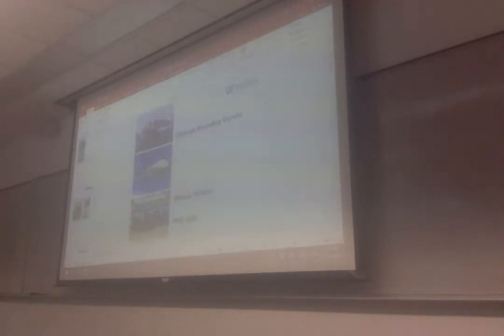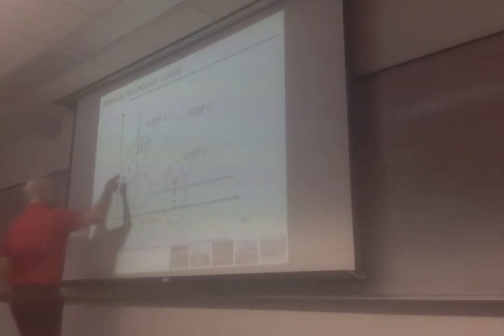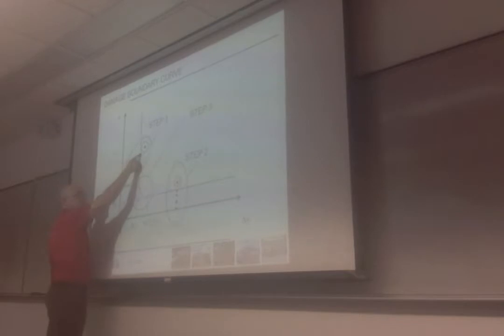Sorry, I'm going to go back to that last slide here. By increasing the drop height from test to test, you increase the velocity change, because with a higher drop height the impact velocity is going to increase, and you increase the acceleration as well because you have a larger velocity change over a constant time. So you go this way, and you don't have damage. Here you have damage. So the conservative approach is to fix this as being the limit.